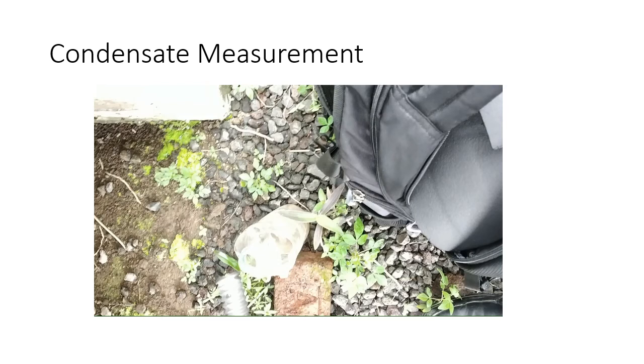Once you are 100% assured that the leakage in the shelter, in the EFC, in the damper, everywhere is plugged, thereafter only you have to check the condensate, and once the condensate reduction is ensured, then you can increase your return air set temperature from 28 or 29 to 32 degrees centigrade.